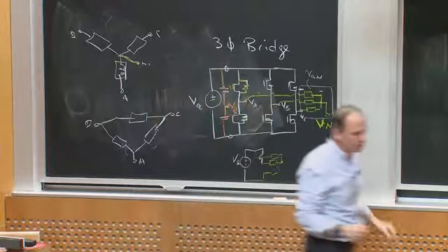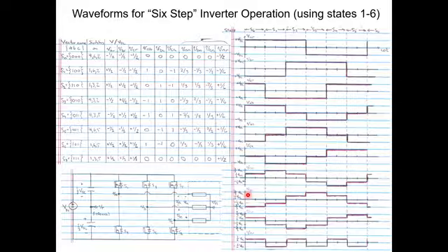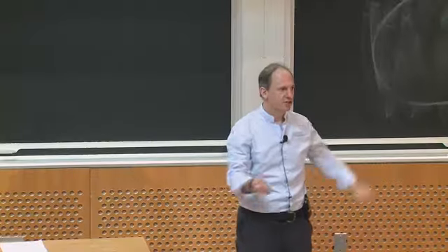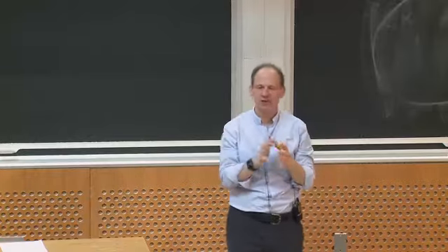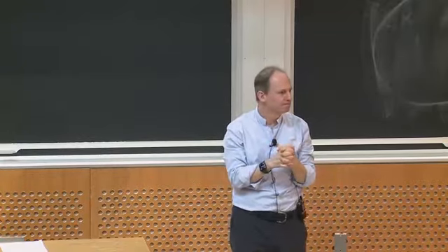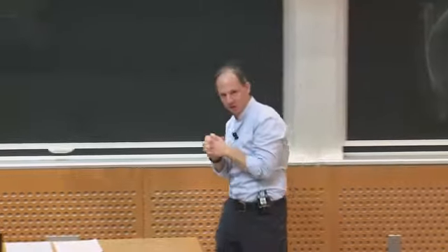And what you can see is that these 3 suddenly take on this 6-step waveform, which looks just like what the diode rectifier was doing. It's just that now I am imposing a DC voltage with that 6-step pattern to, say, the machine or whatever it is I'm driving.